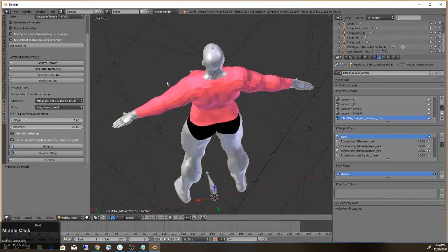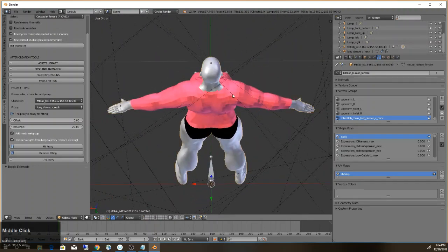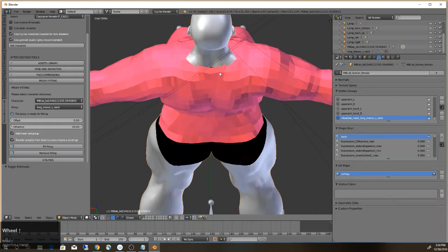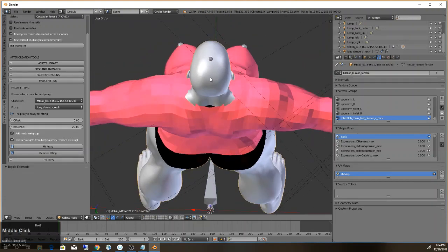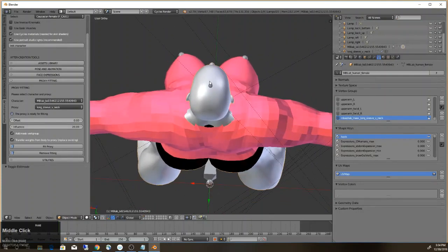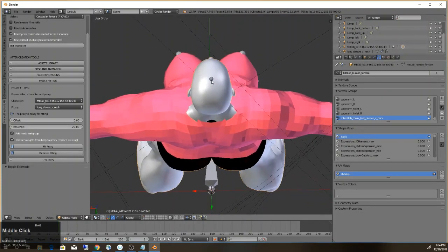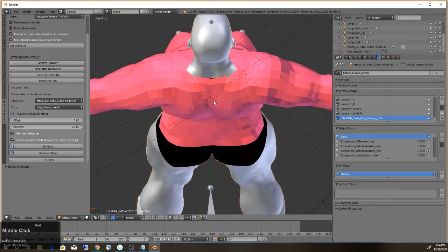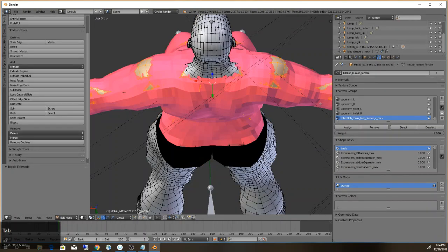All right, but we have a problem here at the neck. We really can't use the mask because we can already see it's kind of created a hole we could see from the top view. We don't want that. So actually, I'm going to even remove a vertex from the vert group right here. I've got the character selected, going into edit mode.